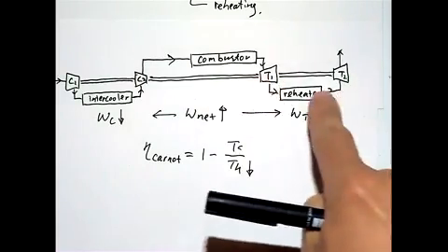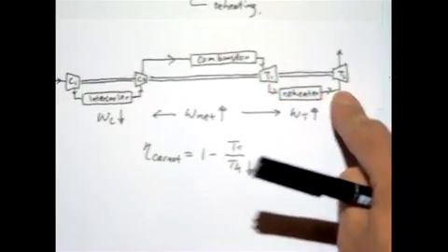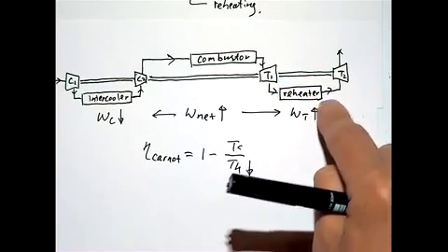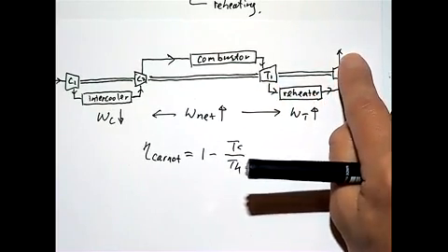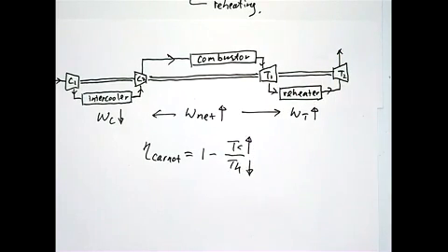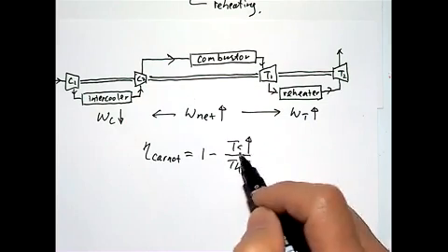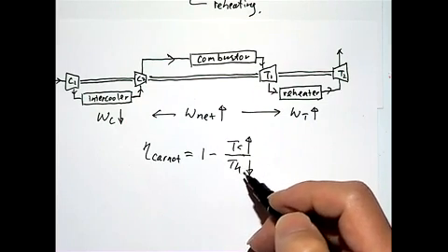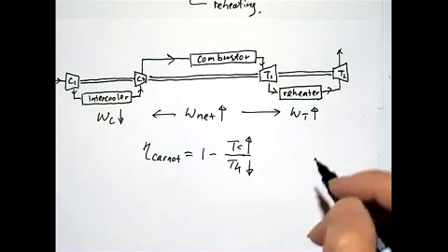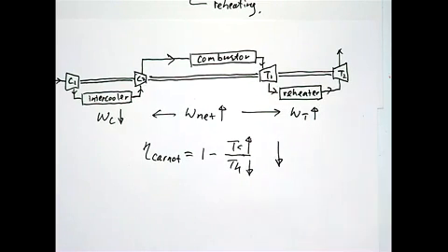And on the other hand, when you're going through two turbines with a reheater, you're increasing the temperature leaving the turbine eventually, right? So in this case, this temperature at the cold reservoir is going up. So if you do any one of these, you will drop the efficiency, but if you do both, then it will definitely drop the overall efficiency of the cycle.